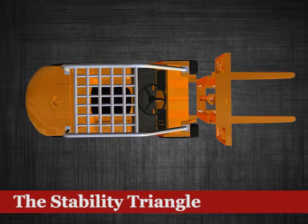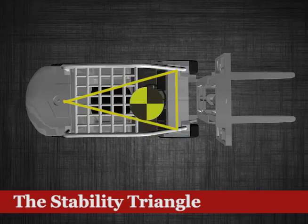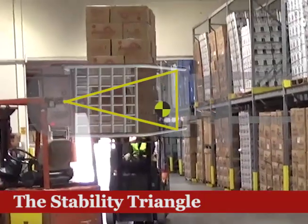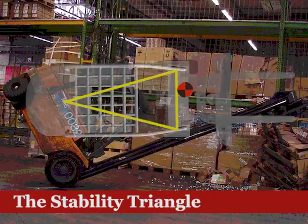Forklifts have a 3-point suspension system. The weight of the load is supported at 3 points, which are the two front wheels, and the center of the rear axle. If you join these points, you get the stability triangle. If the combined center of gravity of the vehicle and the load remains inside the triangle, the vehicle will remain stable. If the combined center of gravity goes outside of the triangle, the vehicle will tip over.